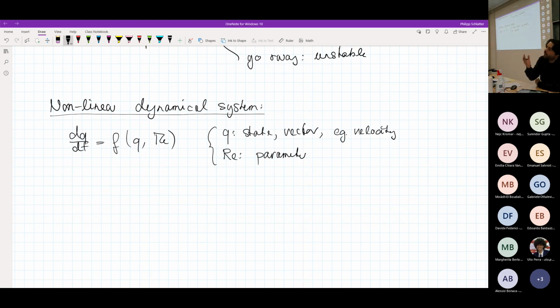So thinking back to the pipe flow that we looked at in the video yesterday, Reynolds made this experiment, and he realized that for low Reynolds numbers, the flow was stable. So there was this constant stream of dye. And at some point when the Reynolds number was increased beyond a certain threshold, he discovered that there was this sinuous oscillation in the flow. So the Reynolds number here takes the function of a bifurcation parameter, which tells us that under a certain threshold it's stable, and above it would be unstable. So that's the idea behind this.